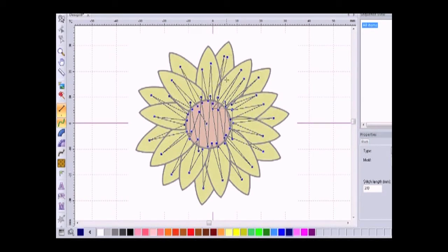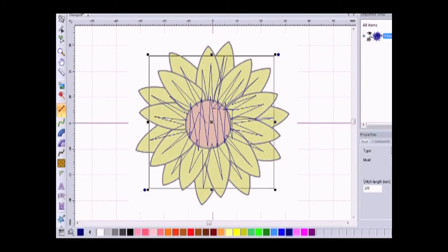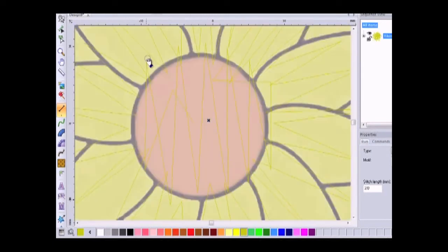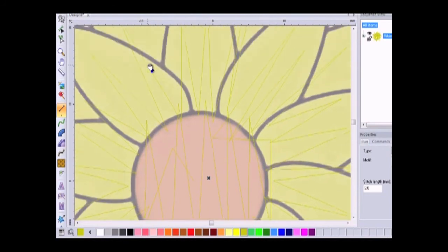So there I've stabilized that area, and I'm going to right click, and you're going to see that the stitches are generated on screen. Well, let's come here and we're going to choose in our sequence view those stitches, and let's make them something a little closer to the color of the artwork that I'm digitizing. Now that I have my underlay stitches put in, I'm going to go down to my 6:1, which is the scale that I like to digitize at.